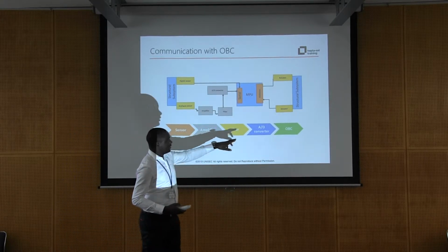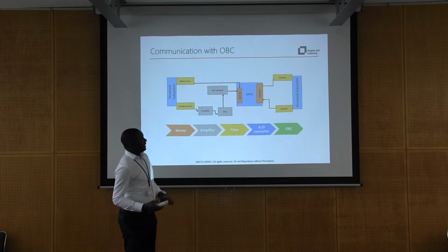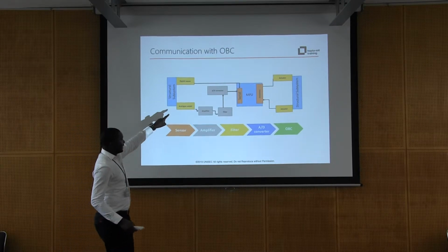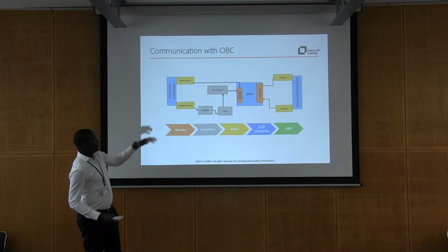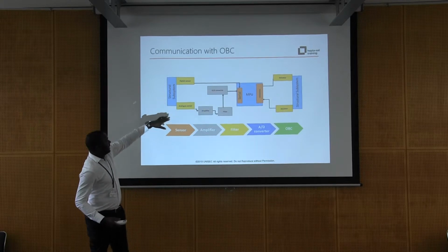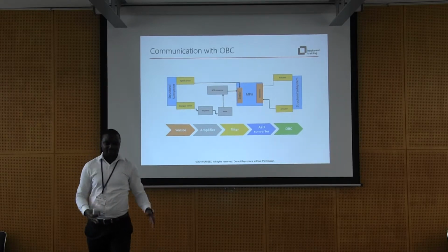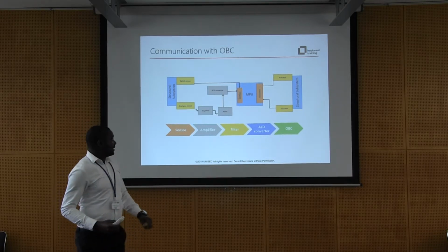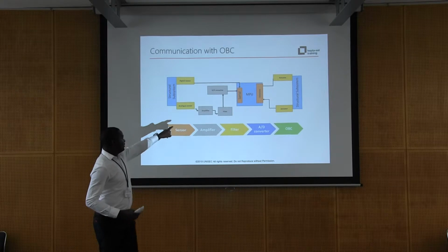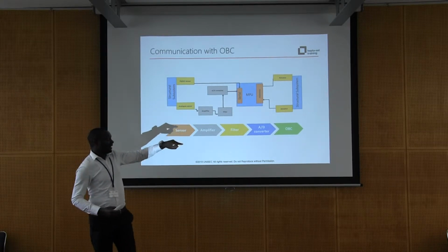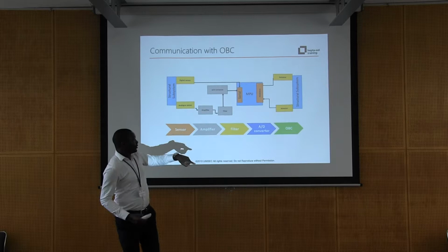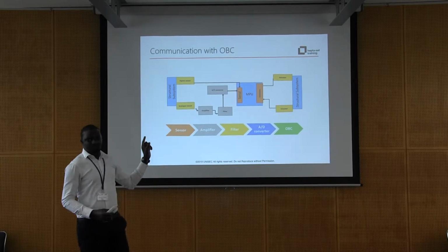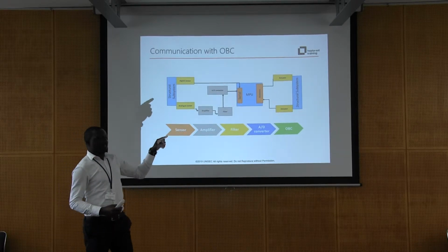In our HEPTA-SAT, we don't have actuators, but in a normal satellite, you might need actuators. But we have the analog sensor. We are going to see which one is analog and which one is digital. And you have a digital sensor. Then the structural subsystem is the outer casing of the satellite, which you will assemble together. When you have an analog sensor, remember that our MPU is digital. So you need to amplify the signal, subject it to a filter mechanism, and move it to the AD converter, the analog to digital converter.